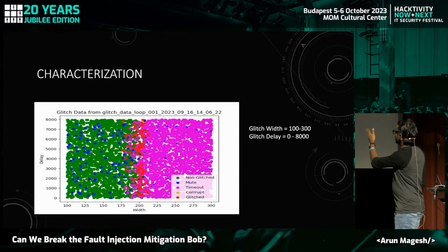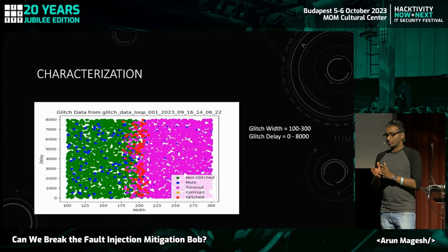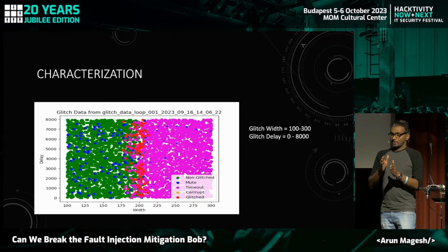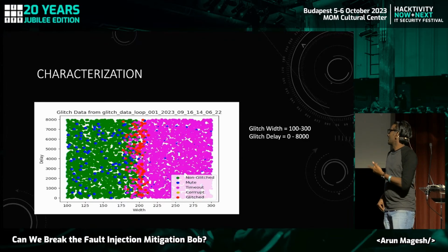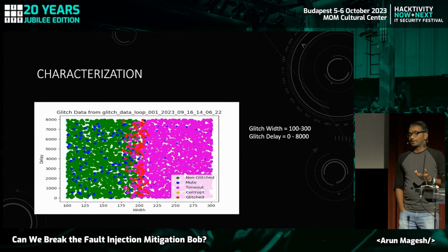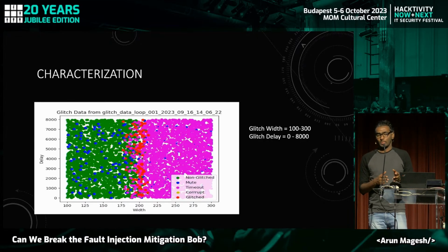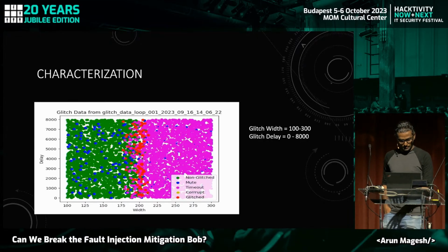So, but if you look in the middle, you can see the red. So red is the sweet spot where you can actually make your chip run and also corrupt the instruction. So in this case, in the middle, instead of getting 2500, I would probably get like 2100, or even, let's say, 4500. So we are basically glitching these instructions to change the code flow, for example.